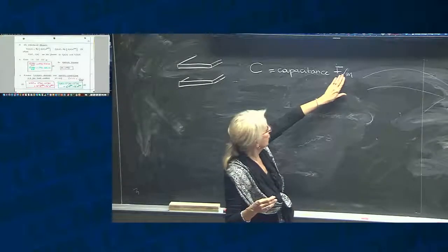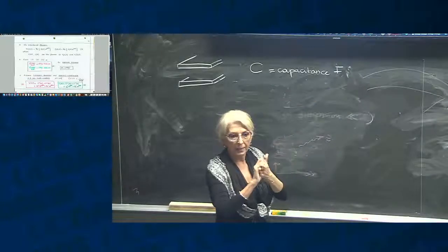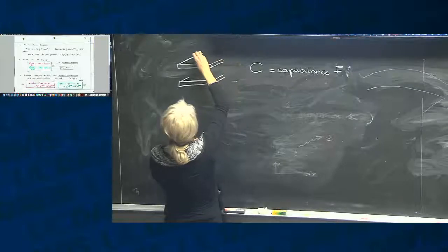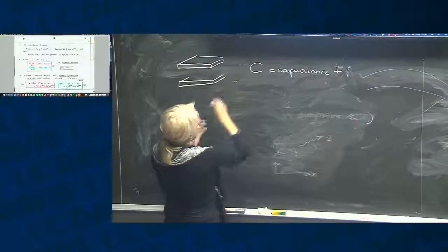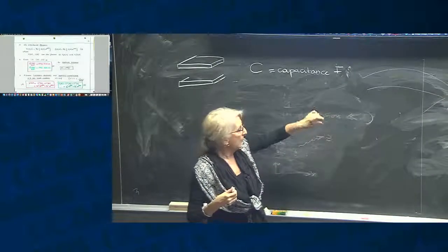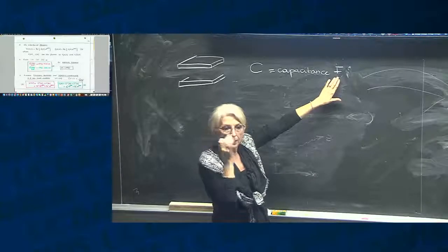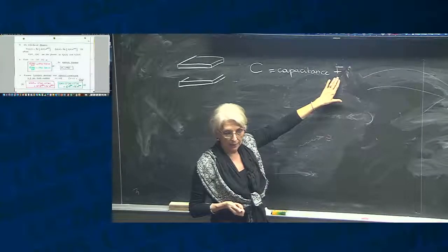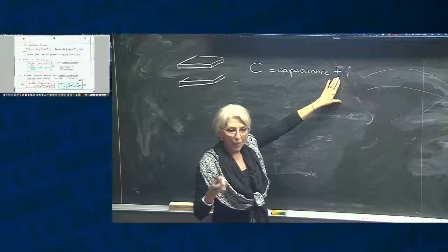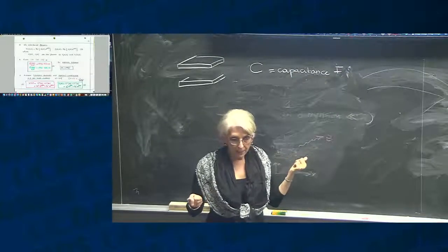Now, we did not show it then like this, but we considered that we had a geometry that was long, with some kind of a length, and we found that in farads, but we always had in mind that it was for this much length of the line, all right? That meant that if the line was twice as long, it would have much higher capacitance.